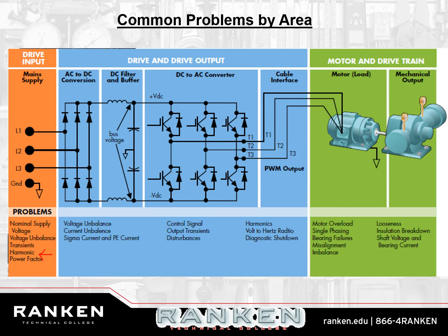The whole capacitive charging and transient voltages and harmonics and things like that on those cables can be causing problems. Is there a reason why you're getting what you're getting on the motor? The motor, we've talked about bad things going on in the motors. The motor's being overloaded. It's single phasing. It's been having trouble. So you can check the motor then.